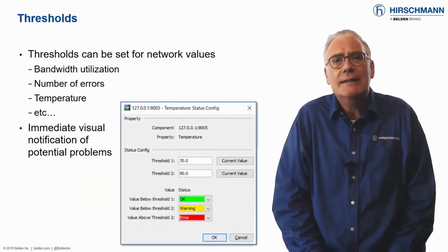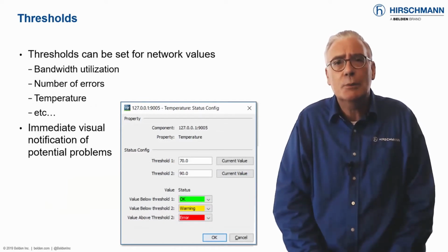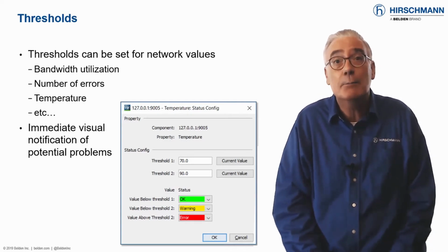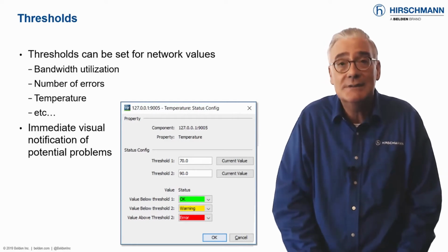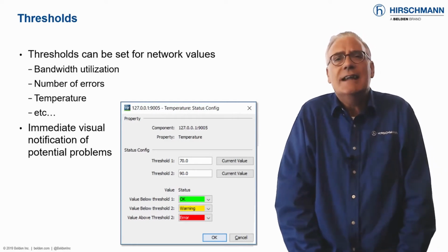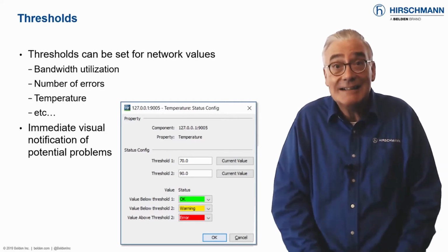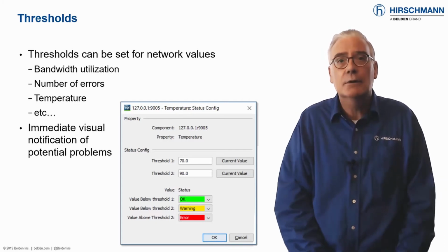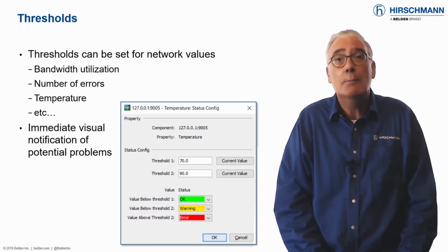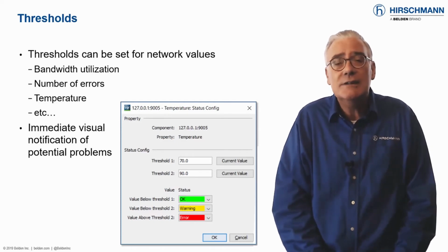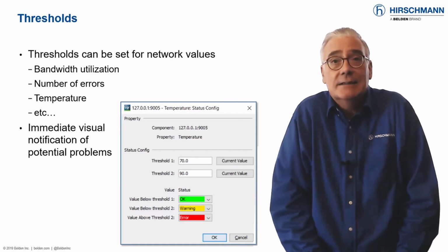As a network administrator, you need to be aware of changes which occur on your network. Physical changes are easy to spot because they will immediately be highlighted in your network management system. Changes in other characteristics are less obvious but can be just as catastrophic. For example, OT networks tend to have predictable traffic patterns based on polling. Changes in network load happen for a reason and must be investigated.